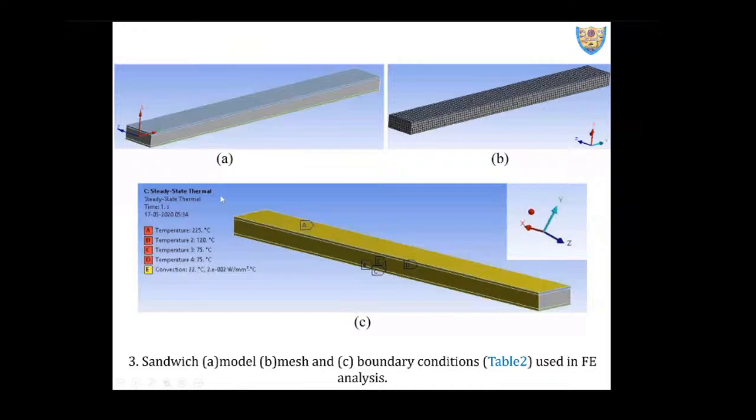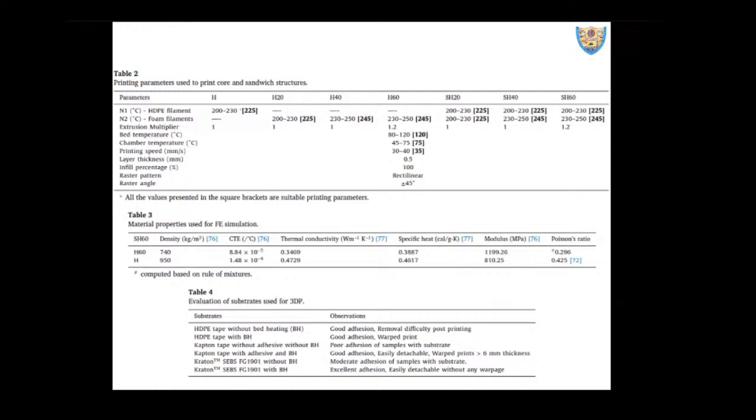it is rather to gain some good confidence that, okay, HDPE can be printed. If I see high thermal stresses, then probably I need to look into the temperature parameters, and we can even change the temperature parameters in the simulation and look around, so that will make the residual thermal stresses minimum. So what you see in table 2 and table 3 and table 4.